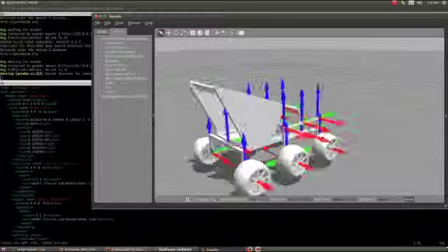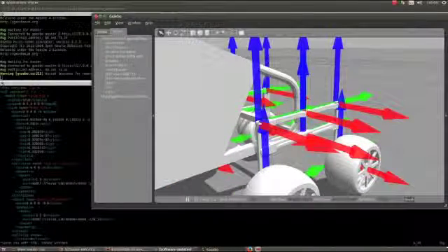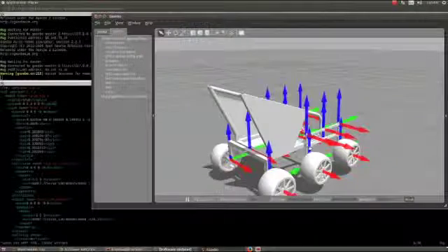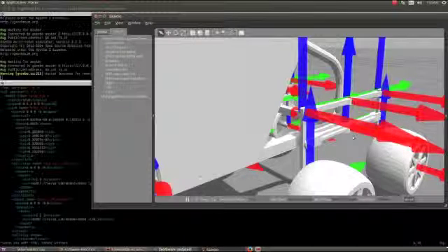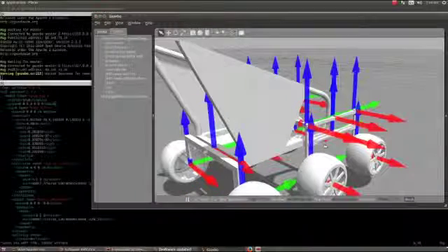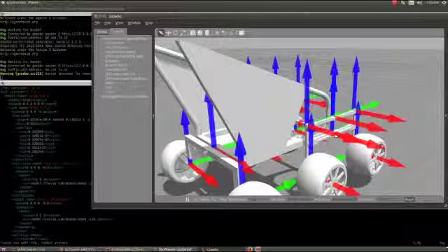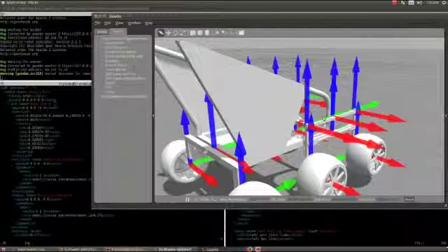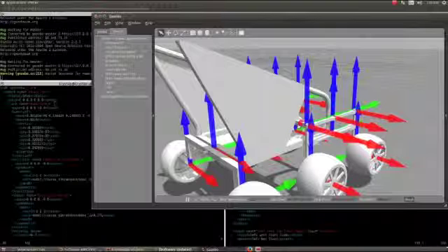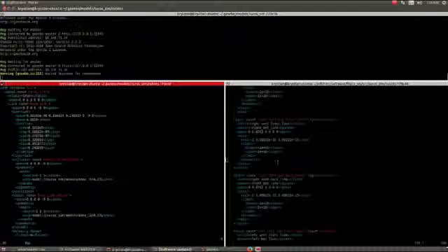The way you do this is you find the position that intersects between the joint that was created here, the joint that was created here, and the intersection between these two linkages. Just to save time, we see here that this is a manual one. I copied and pasted this from, for example, this joint here that was part of the export from SolidWorks. I rewrote the name, the child linkages, the parent linkages, and then just kept pasting it.